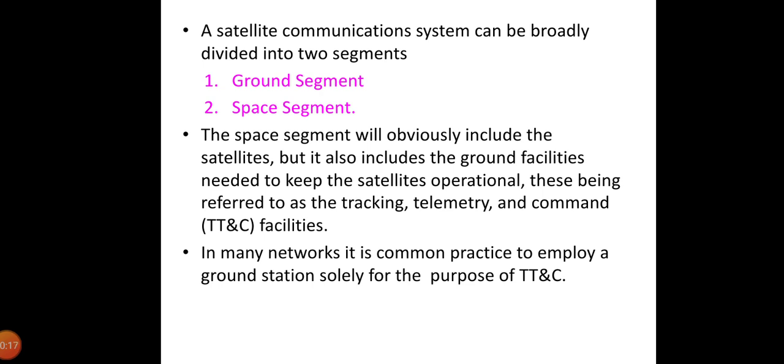The space segment will obviously include the satellites, but it also includes the ground facilities needed to keep the satellites operational. These are referred to as the tracking, telemetry, and command system, that is, TT&C facilities. In many networks, it is common practice to employ a ground station solely for the purpose of TT&C.